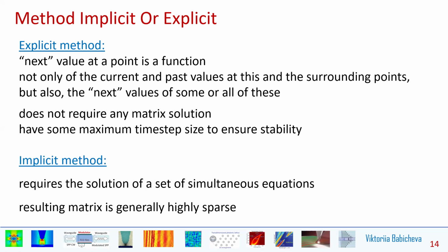On the contrary, the implicit method always allows stable time steps under certain conditions, the size of which must be regulated only by precision criteria and not stability criteria. In return, there is the disadvantage that a system of equations involving all degrees of freedom must be solved, making the method costly and difficult to parallelize.